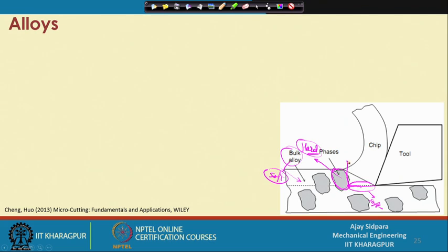will suddenly shoot up, because you are coming across this hard grain and you have to cut or pull out this grain. Many times what happens is that suppose the grain is located something like this, where a very small portion is located below this particular area and your tool is at this location. At that time the whole grain will be pulled out, because it has a high tendency to be a part of the chip compared to the part of the workpiece material. So, instead of a straight line, the machined surface will be something like this, and you can consider this as a pull out.